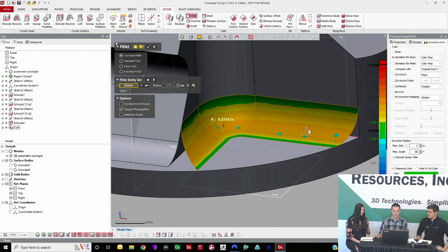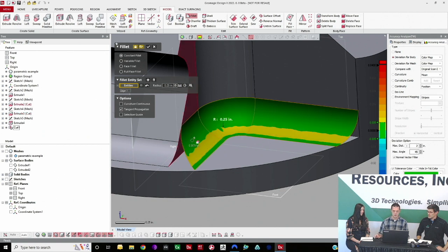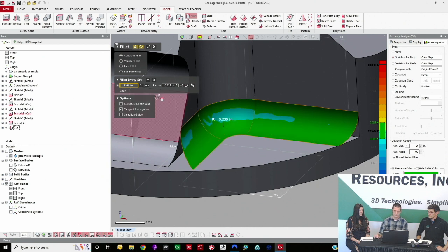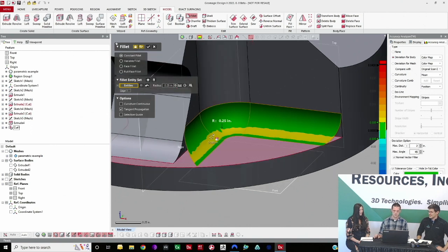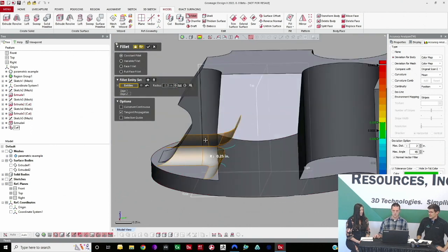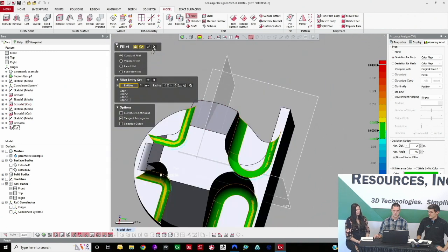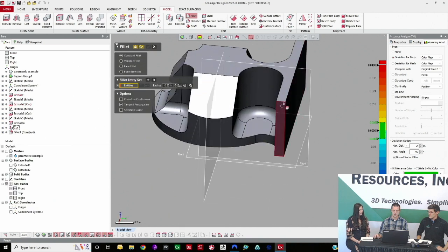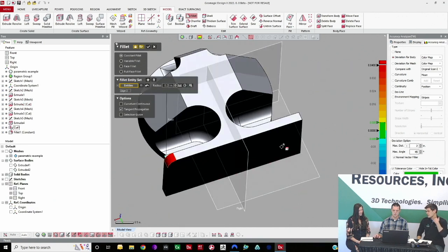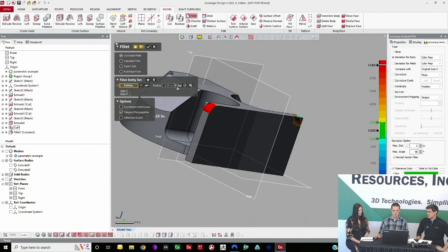I'm not sure it's done the best job, but we can get that to fit a little bit closer by using our accuracy analyzer. So you can see I'm maybe 10 thou off. Let's try like 0.25. And you can see 0.25 is much, much closer. Yeah, probably just going to do a 1/4 inch actually. And then here, wow, 1/4 inch is going to be a little bit too small.